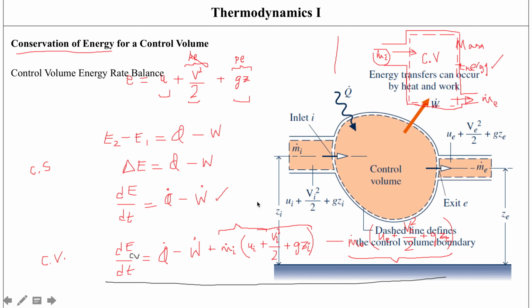So now that we have this equation for a control volume, I could also represent it in terms of the system being shown here. This is our control volume. This incoming fluid element, which would be incoming at a certain mass flow rate, would carry this energy within it when it's coming in. And the exiting mass flow would carry this energy when it is leaving the control volume.